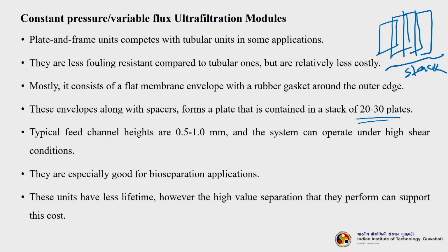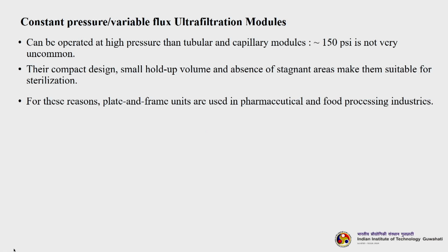So, they are especially good for bioseparation applications. Bioseparation usually means separation of proteins and antibodies. These units have a shorter lifetime, however the high value separation that they perform, for example bioseparation, can support this cost. They can be operated at higher pressure than tubular and capillary modules. Usually 150 psi is not uncommon.